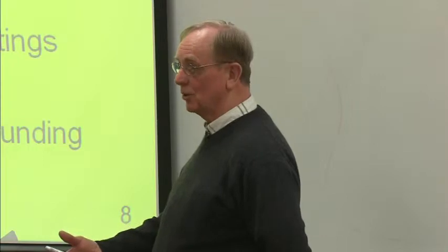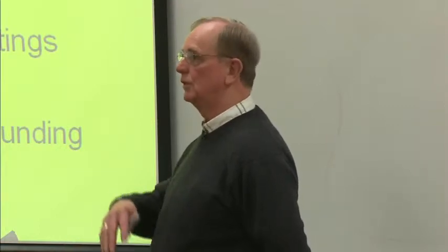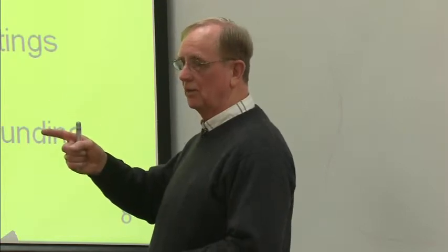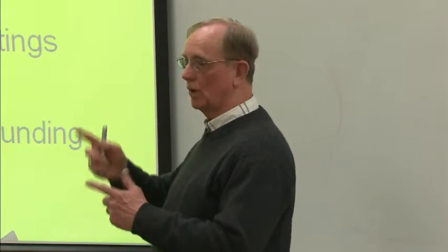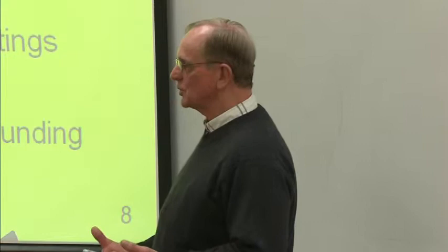Most of you are familiar with a ground fault circuit interrupter in your home today. Anybody ever trip any of those in their home? Usually got a button to push to reset it. Those are set to trip at 5 milliamps of ground fault current, current flowing outside the normal system. In other words, on your single phase residential application, current's coming in on the hot line, the power line, and it's going back on the neutral. So what comes in goes out. It's a flow that's easy to measure, to compare the two and see if anything disappeared.